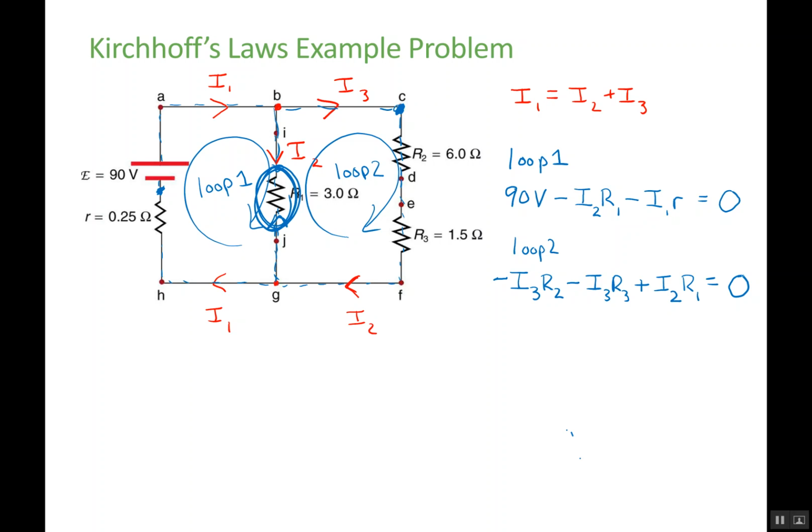So now it's a lot of algebra. We'll practice it in class, and you'll get practice in homework. But we could solve for I1, I2, and I3 by doing substitutions to eliminate 2 of the unknowns in one of these equations, so we can solve for the third. All right, so that concludes this lesson. Again, in class, we'll do some more practice actually solving these equations that you get by applying Kirchhoff's current law and Kirchhoff's voltage law.